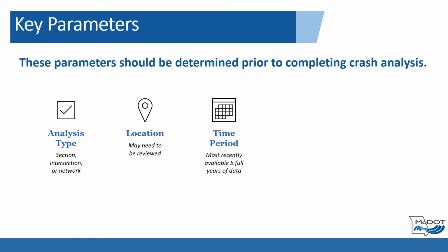Time period. Typically, a study period of the most recently available 5 full years of crash history data is standard for crash analyses. However, there are exceptions to this typical practice. Always check with MoDOT safety engineers to ensure reasonableness. Study limits.